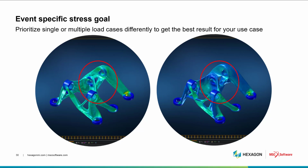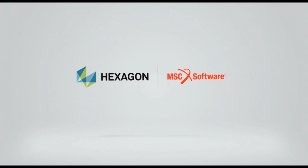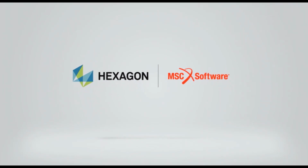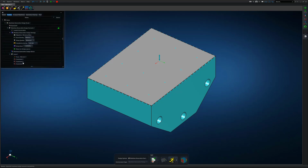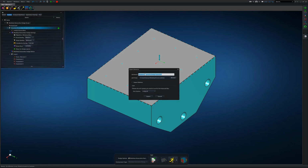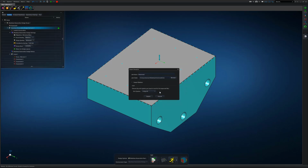And we have another feature I would like to introduce to you now. It's the command line optimization option. Now you have the option to not only start your optimization directly in MSC Apex Generative Design, but export your already created model setup and run it in the background. For this, we are having a look at the bookshelf tutorial again and at the already prepared model, and we are just going to export it.